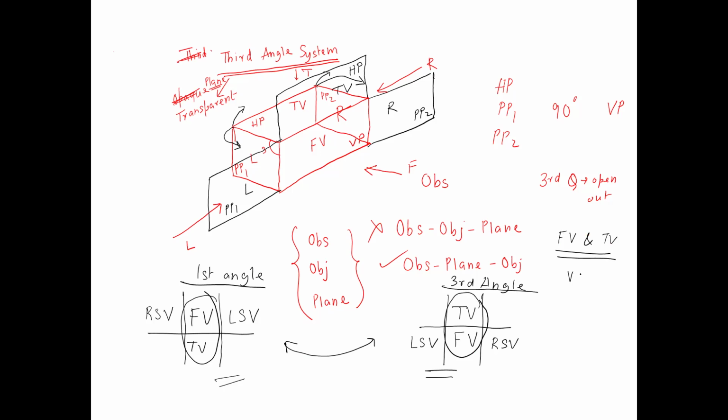But when two views are given to you like this, view 1 and view 2, arranged in a column vertically, then these two views can be a combination of front view and top view. None of them can be side view. Because on top and below any side view, can you find any other view? The answer is no.